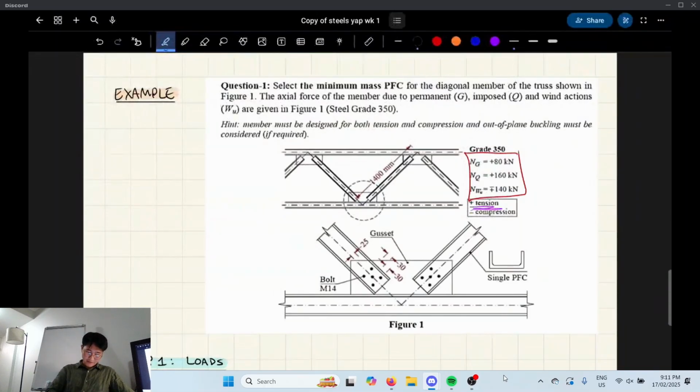What about this one? It's wind. But what about the right hand side here? Plus minus, minus plus, sorry, my bad. It puts everything in tension and compression, because you have to check wind both ways. The wind goes in either direction. It will literally be pushing and pulling, so you're accounting for both directions.